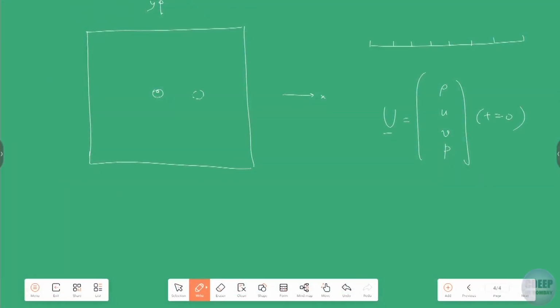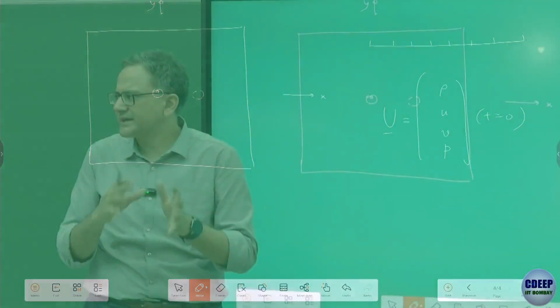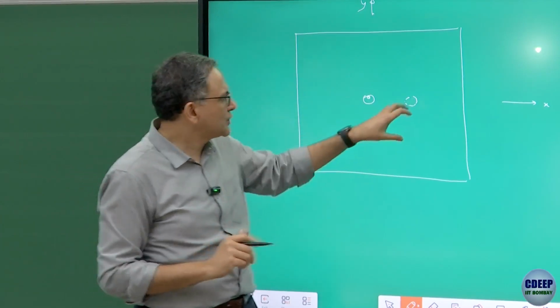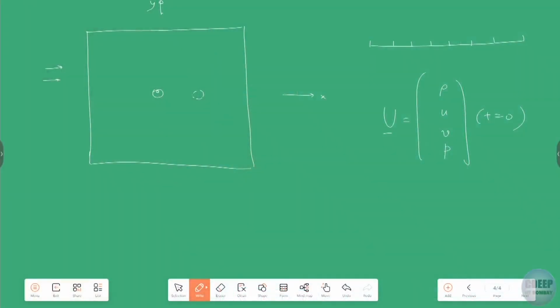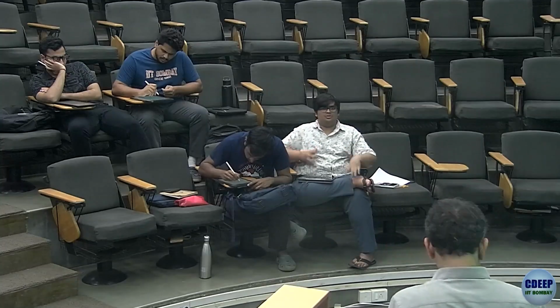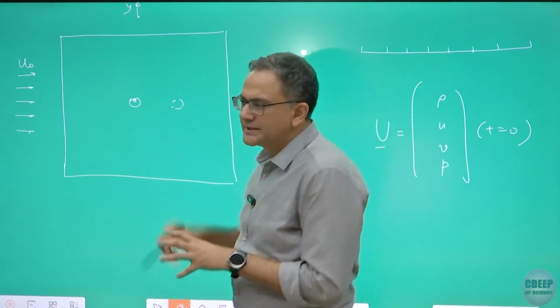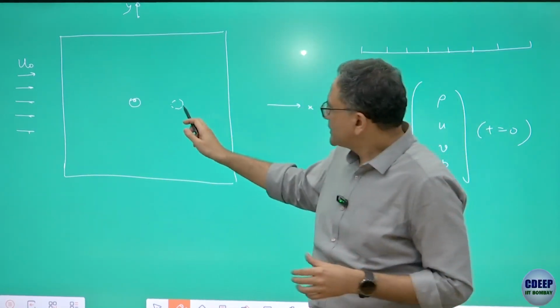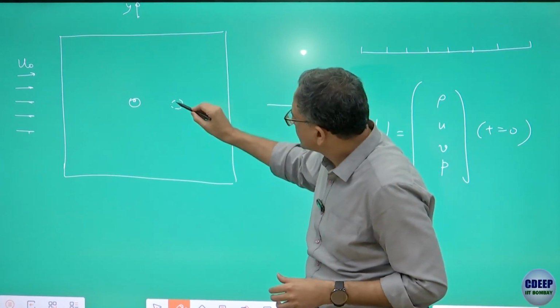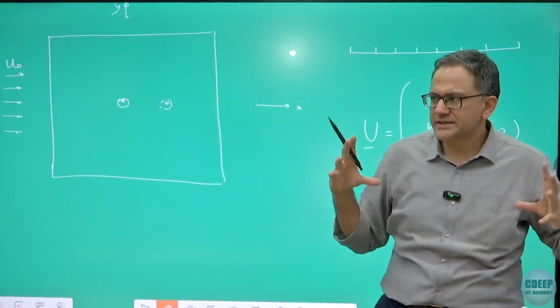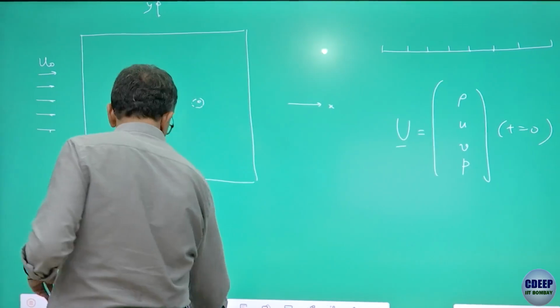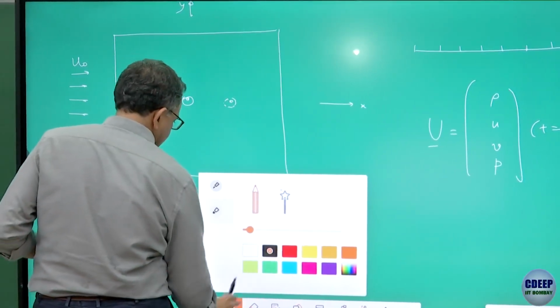This will be the vorticity and entropy component, because all that sneezing was at one locality. So the vorticity and entropy will be all together. Whatever the shape of that disturbance might be in space, they will go together because there is a u0 that is convecting them. So what about the propagation outwards of sound? We will do that. It's not done. So they'll separate out. Notice again that the shape did not change, neither the size, but then there will be the sound wave also.